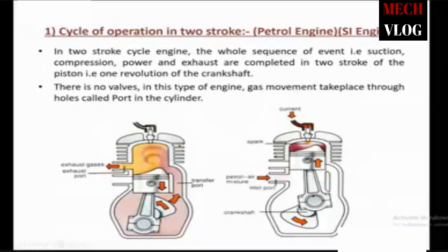There are no valves in this two-stroke engine, only ports. We have a total of three ports. The first one is the inlet port, that is the petrol inlet port. The second one is the transfer port, and the third one is the exhaust port.